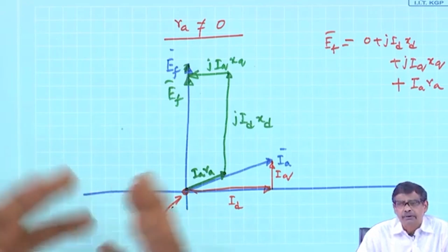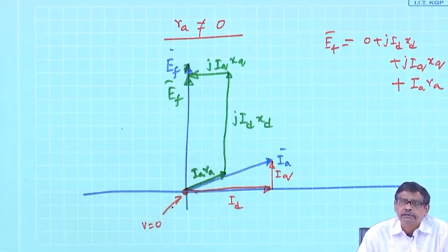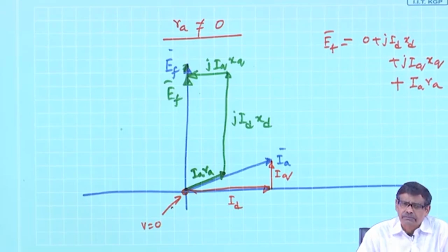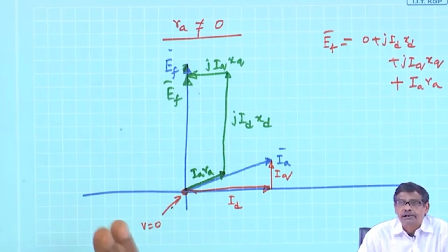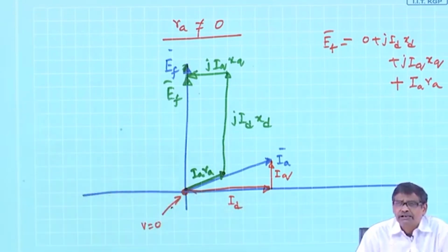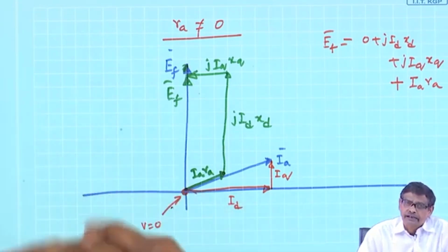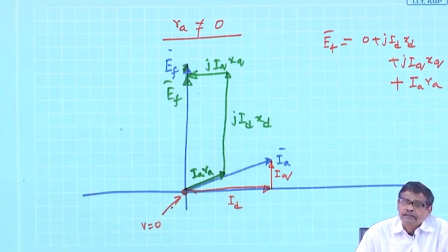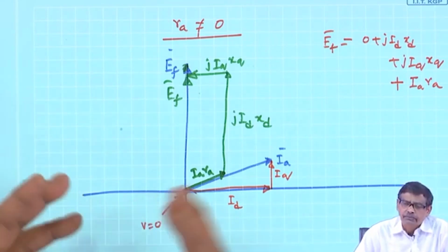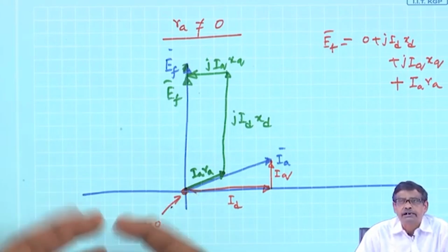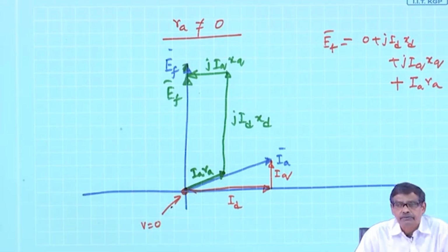So, I discussed armature windings, not in too much detail, but very basic armature winding, 60 degree phase spread, 120 degree phase spread, 3 phase distributed winding. In an induction machine, in the stator and rotor, this type of 3 phase windings is used, and if the rotor of a 3 phase induction motor has this type of winding, it is classified as a slip ring induction motor.